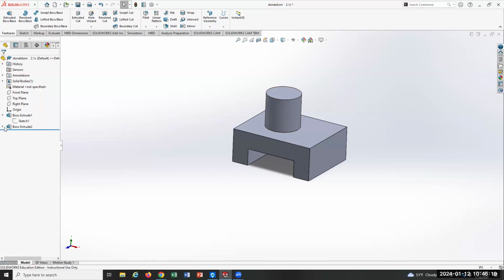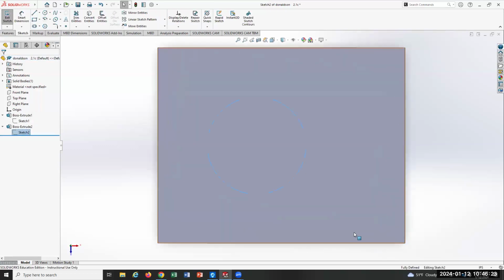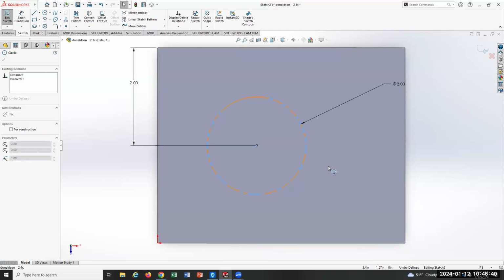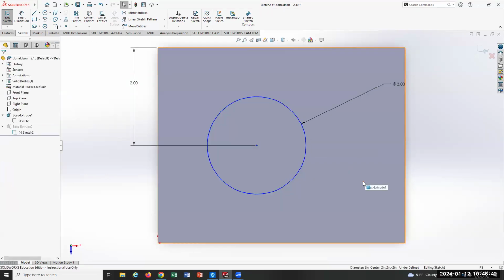Like now I could go back to this sketch and fix it, right? Actually, this looks good. I'll leave this one here. I'll get rid of this one. And I'd like to move it to the center, right? Once it's blue and not controlled, you can actually just kind of grab it and move it around, but that's not very accurate.